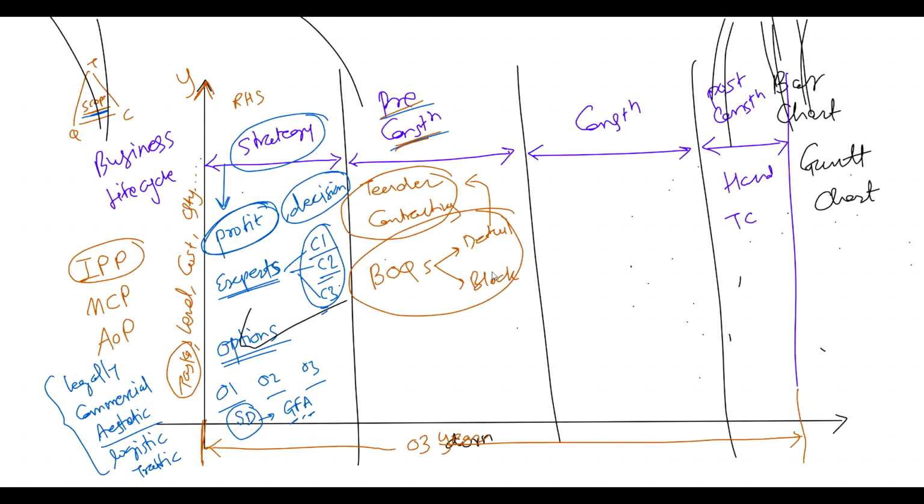In construction, whatever you are going to plan will be decided earlier, in pre-construction. I repeat, whatever sequence and activity list you are going to prepare for construction activity needs to be decided and planned in the pre-construction phase, strategically, technically, and from a resource point of view. Let us take an example: whether you are going to do the RCC framework with which technology, whether conventional or aluform.